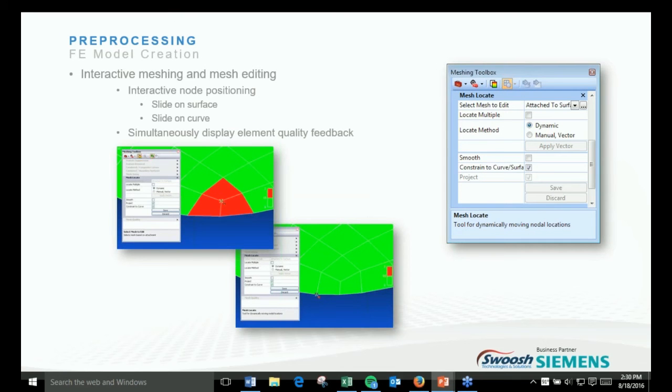So for very detailed mesh adjustments, you can even manually move individual nodes around the underlying surface geometry. This becomes really critical at times. FEMAP ensures that they adhere to the underlying surface of the curve, which can be a useful tool to improve the element shape, so that it can pass the selected element quality criteria that you've chosen for your mesh.